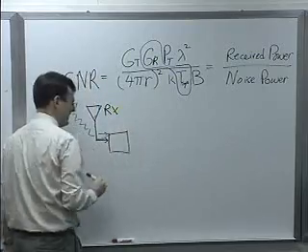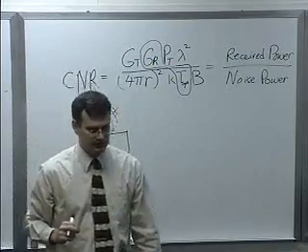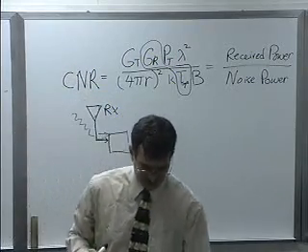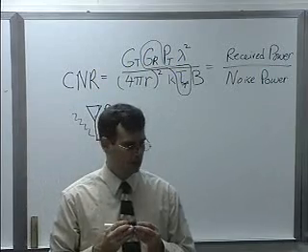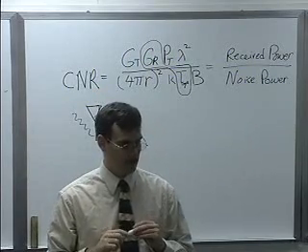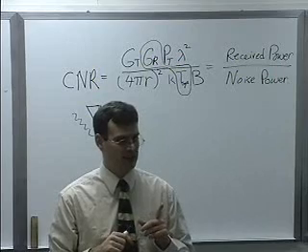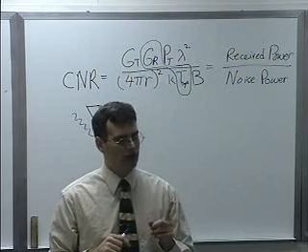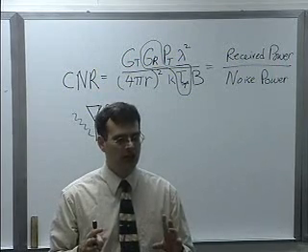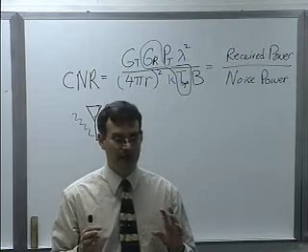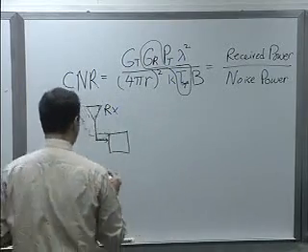What's the first thing any RF engineer does after a receiver antenna? Power amplifier or low noise amplifier. That's one of the steps. There's probably one other thing you want to do before that. Bandpass filter. That's right.